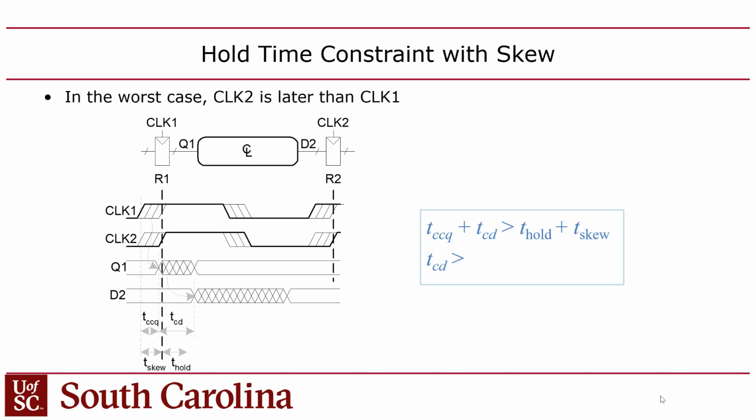We're saying, well, the hold time was 60 picoseconds, but the clock skew might be 20 picoseconds. So I'm going to add that as an additional constraint to the hold time. I'm going to make the hold time more constrained, basically, to account for the skew, right?